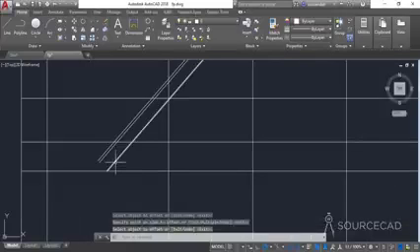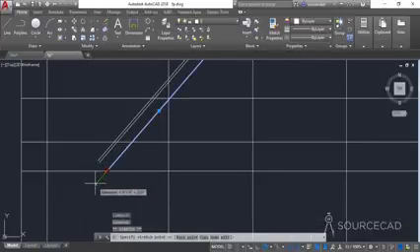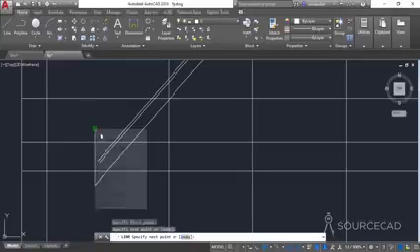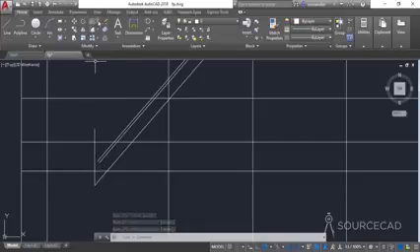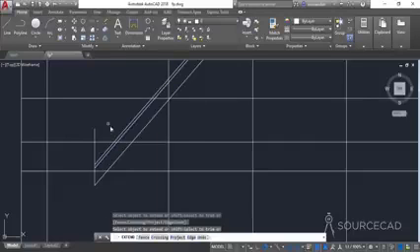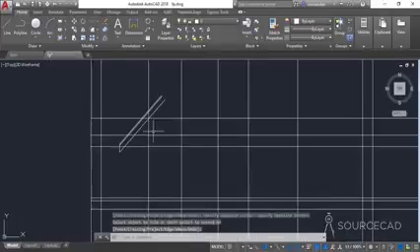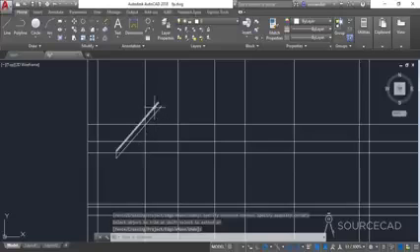Now let's stretch this line a little bit towards this side and just make sure that it follows the same linear curve and it does not deviate from that linear path. Alright, and then I'll make a single horizontal line just like this. And now I just wanted to touch these 2 lines to touch on this one. For that I'll select extend, press enter and click on these 2 lines. And now select trim, press enter and trim this line. That's no longer needed.